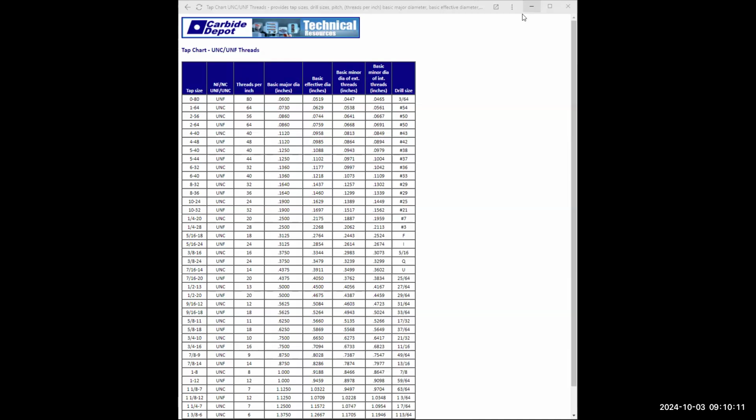Enter. Now those are called center marks. Now we need to have center lines for each one of these holes. Sometimes they're called bisector center lines from Inventor. You remember that. So we're going to go to center line and I'm going to click, watch. Click this line, this line. Don't worry about how long it is yet. Enter. Click this line, enter.